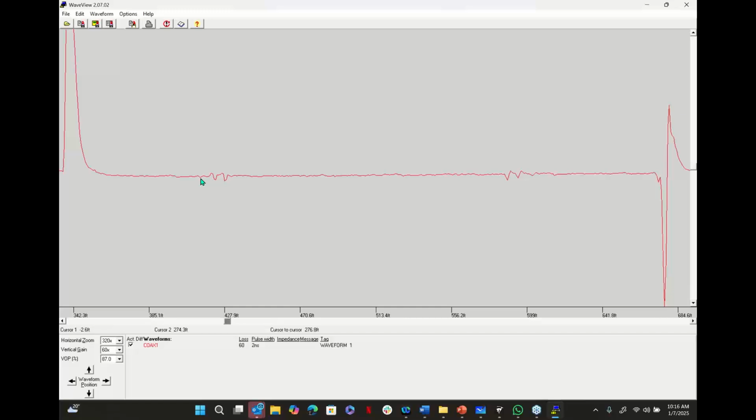The reason I say ghost reflections suck, because I said this at the very beginning, most things that you're looking for are easy to find. Knowing that, this is obviously damage, but you would also look at this, and this is obviously damage as well. So if you dug up this hole right here, you would find your problem right here. But if you dug up this hole right here, this is where you start to get a little bit angry, because there's nothing there, and I mean nothing.